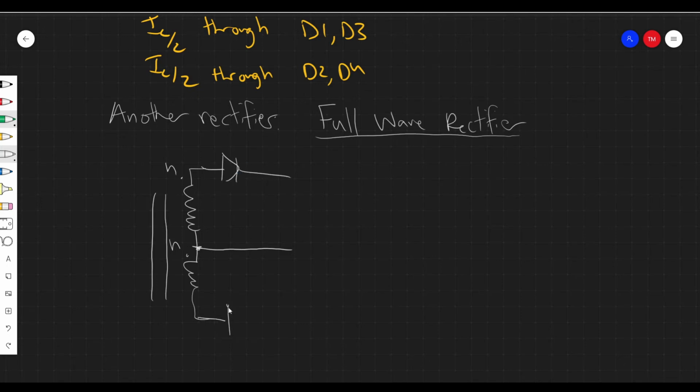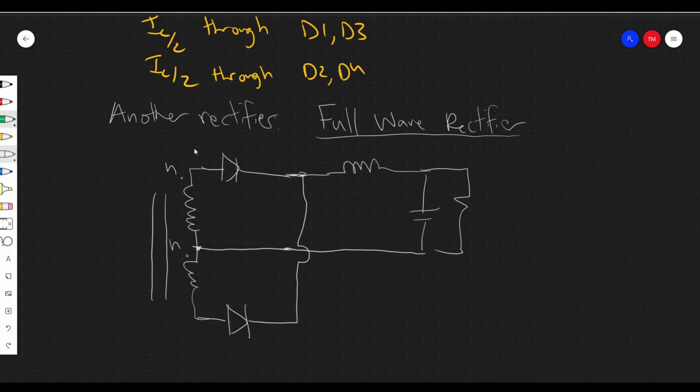And what you do is you add diodes, right? That connect to the same node actually. Right, so they both connect up here. So this is like our positive node, similar for the buck, right? And this center tap is kind of like the ground node of our output, right? So again, we have L, we have C, and we have V out over here, and this is our load.